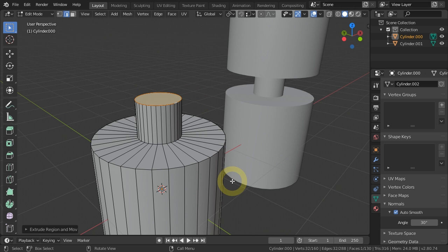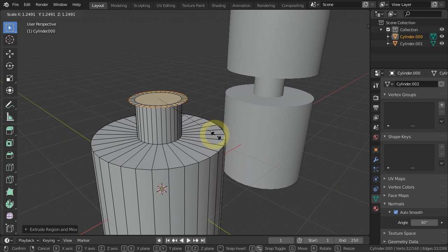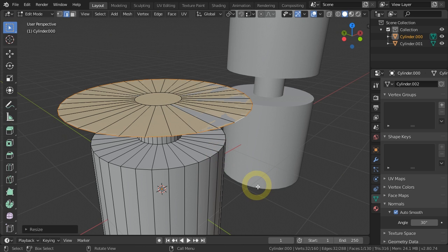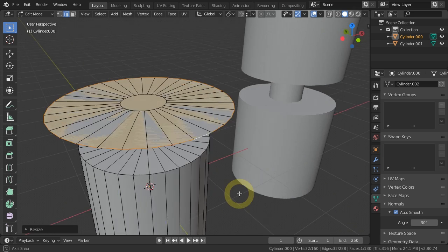Now I'm going to give you a false example. If we just press S, then while scaling like this, we hold the Control key to turn on the snapping mode. Notice it will snap, but only based on the mouse location and not really aligned to the z-axis.